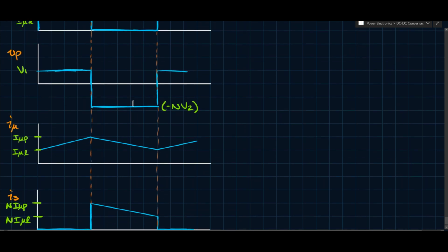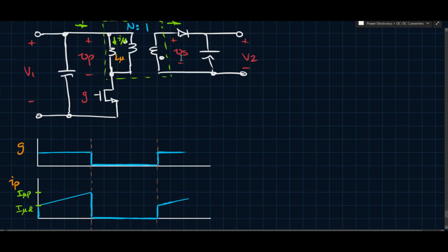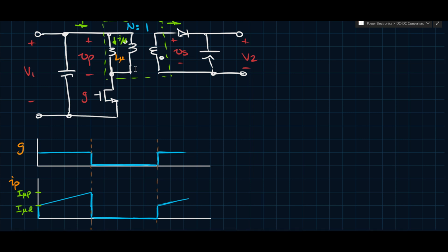So again, like I mentioned, this converter's transformer is required to store energy, and they're usually called flyback transformers. They're a special kind of transformer. They usually just have a lot of windings. They're wound on a certain type of core. You can find them in different types of CRT monitors, for instance. So if you have an old TV or an old computer monitor, you can open it up, and there are flyback transformers in there. I would highly recommend that you be careful with them, because they can produce very high voltages. They're often used in Tesla coil type hobby projects as well. They're very useful for that. But again, please be careful with that kind of stuff, because they can produce very high voltages, and those can be dangerous, and usually are dangerous.